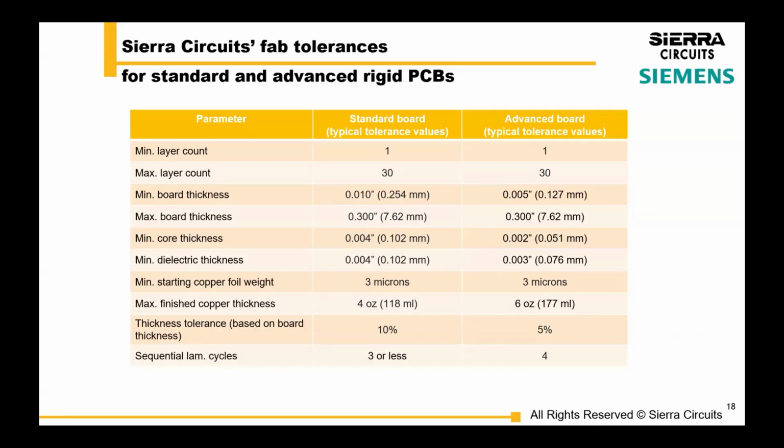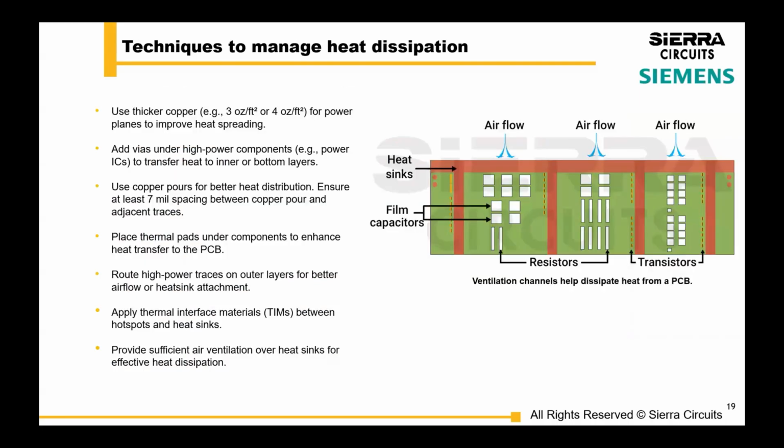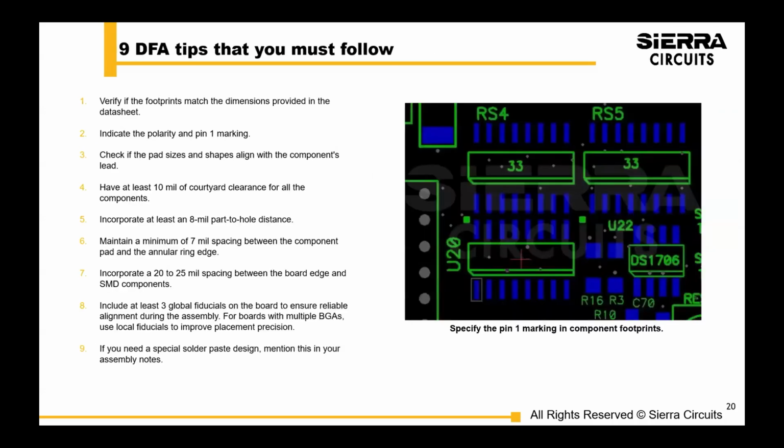Some general capability guidelines and tolerances. I think also important is understanding, are you designing your board properly with thermals? Are you managing your heat properly? What are you doing with your stack up to manage the heat properly? So all these things are important in your DFM to make sure that you can assemble it and the board functions properly in the field.